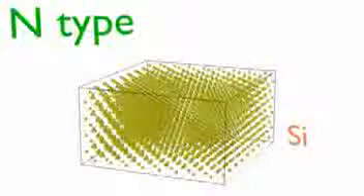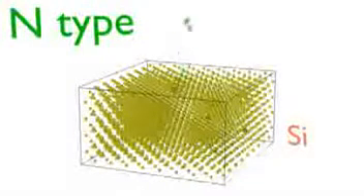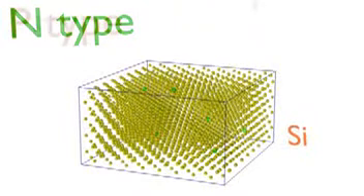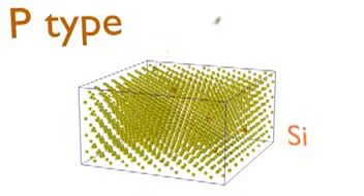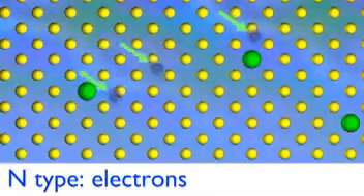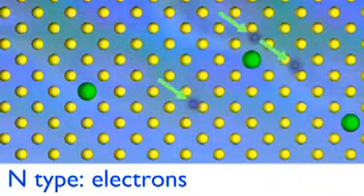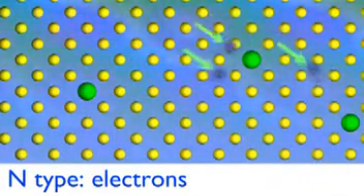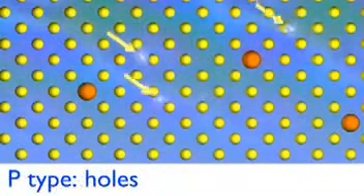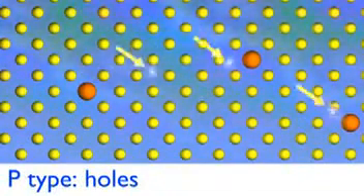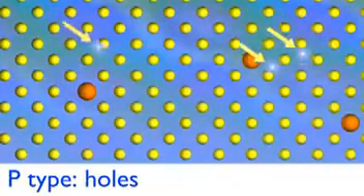The MOSFET is manufactured in a silicon substrate, one of the most prolific materials in the Earth's crust. The advantages of using a semiconductor material are the following. Firstly, we can change its conduction capabilities by the controlled addition of impurity atoms. Secondly, it can have charged particles of different electrical signs, according to the type of impurity added. These particles are called electrons and holes. Electrons having a negative electrical charge, and holes having a positive charge.